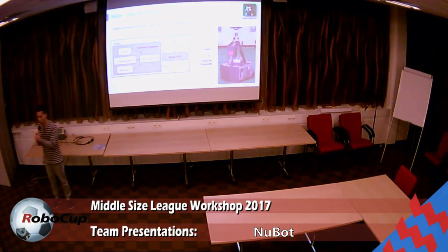But if we want to process the information from the omnidirectional camera and also the Kinect, you consume so many resources. So we try to use a TX1 here, and we also use the ROS framework. The TX1 processes the data coming from the Kinect, and it uses CUDA parallel computing based on the GPU. After this process, you transmit the data using ROS messages to the industrial computer. The ROS master is in the industrial computer, and they are connected using a wire cable. The communication middleware is very easy because it is based on ROS, so we just transmit the ROS messages.